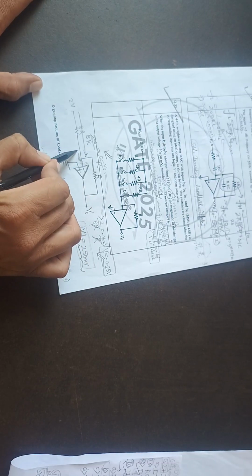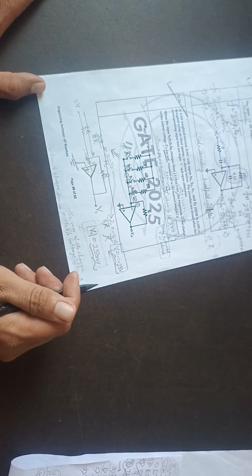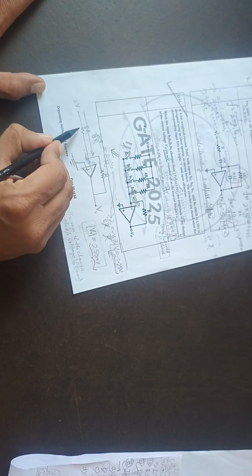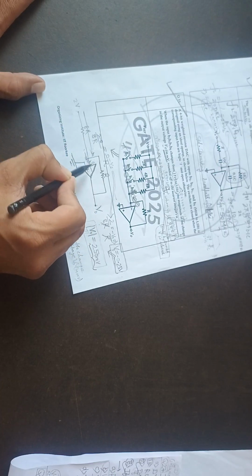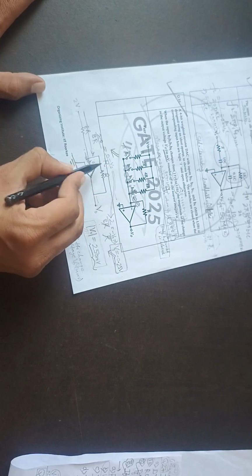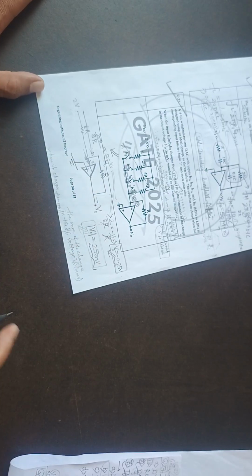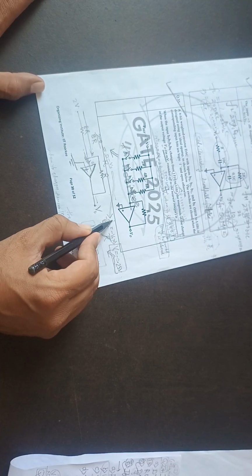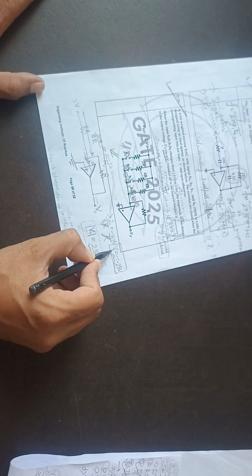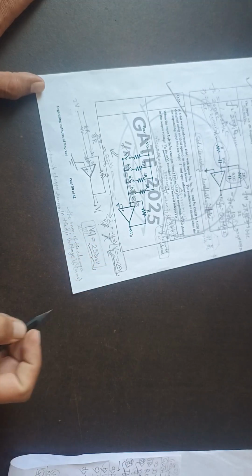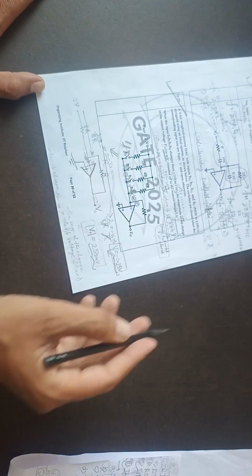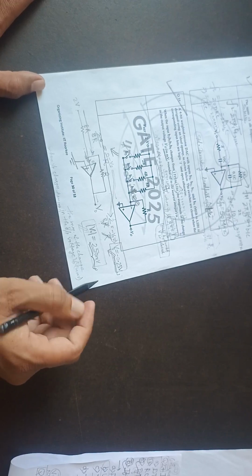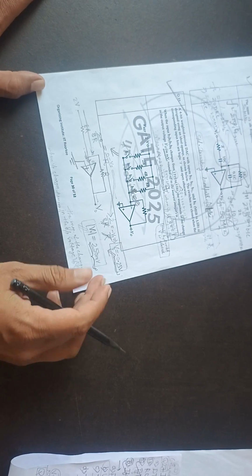So basically this circuit will simplify to 2 volt, 8R, and then this R, which is a simple ideal op-amp problem. This current is equal to this current, so (2 minus 0) upon 8R is equal to, because this current is 0, this will have to go to this part only, so 0 minus V naught upon R. So 2 by 8R is equal to minus V naught upon R. R cancels, so 1 by 4 is equal to minus V naught, so V naught is minus 0.25. We need to find the answer in millivolts, so the magnitude of V naught will be 250 millivolt. So the answer to this question is 250 millivolt.